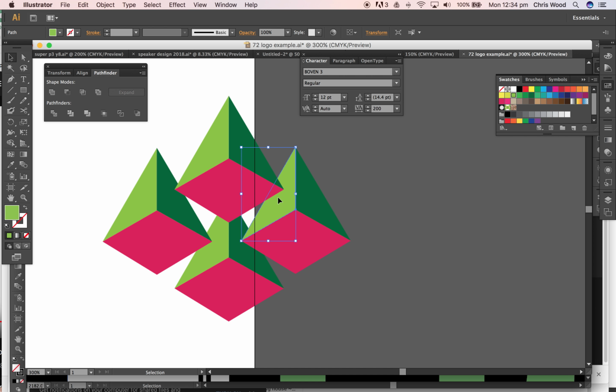Okay, so there's a couple of different ways of doing it. I often don't mind if it's not too complicated, I'll select the whole thing. Like in this case, you could use Minus Front and Back, but I'm just going to go Divide. And Divide is basically going to chop the whole thing where everything overlaps. Okay, and that's actually okay because when I want something like that pink square to be solid, I'm just going to select that again and turn it solid. And I'm just going to push that away now. Actually got a little bit there. I'll just group that in with it.